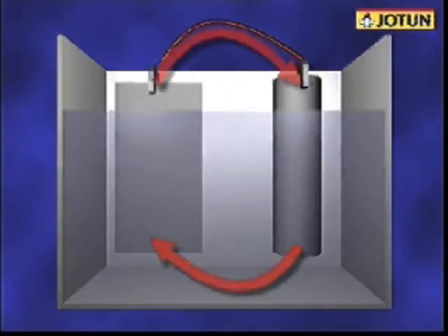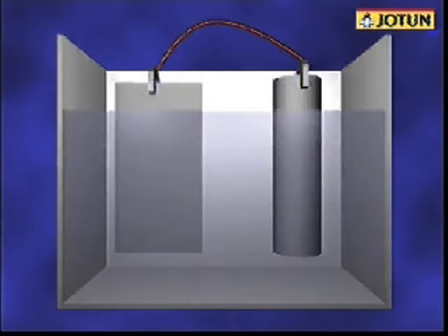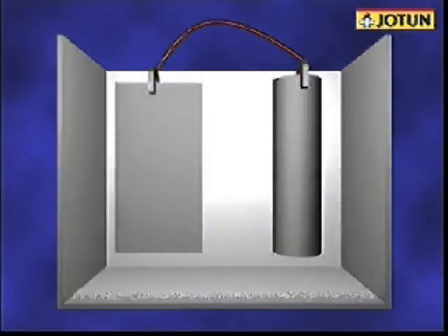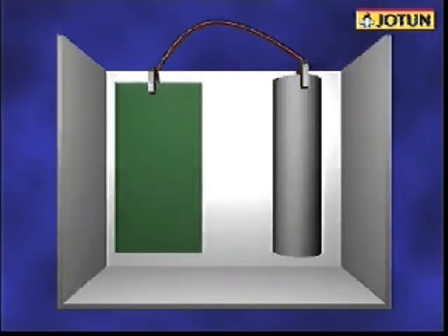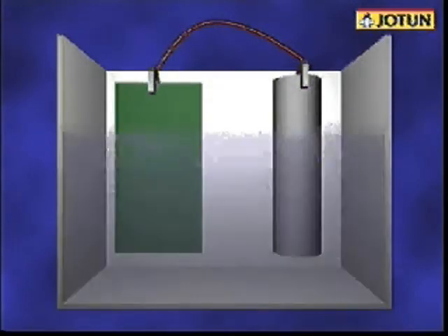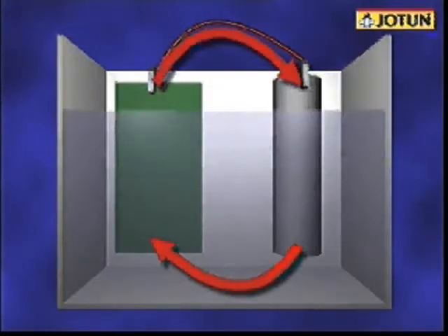For corrosion to develop, a corrosion cell must exist. If we break the circle, the corrosion will stop. Protection will be achieved by creating a barrier between the metal and the surrounding environment. An anti-corrosive paint can form such a barrier. Obviously, a thick coat will protect better than a thin layer. Once applied, the corrosion circle will be broken.